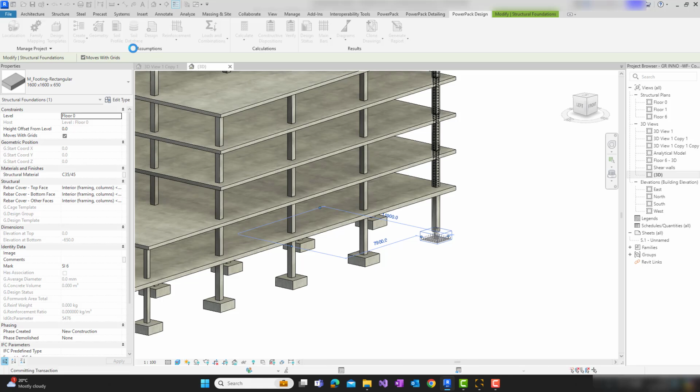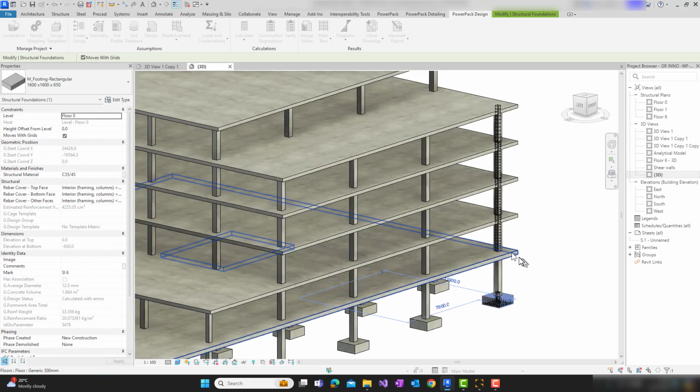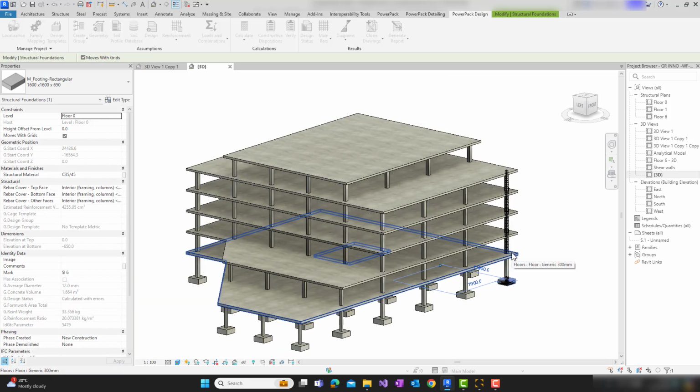So that is the workflow from taking our concrete design here in Revit, taking it to Advanced Design, quickly doing the analysis. Obviously you could add more loads where they're missing, etc. And then pull them results back and then utilize our analytical results to generate our rebar cages.